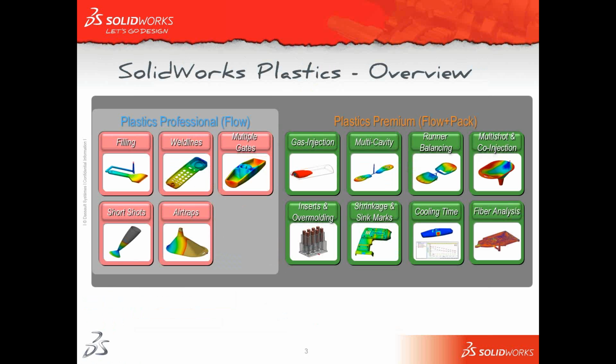This is where, if you've got 2 different sides to a casing, as an example, that are different volumes, you ideally want those to fill at the same rate, just to ensure that they cool at the same time, and you're getting a continuity of quality in those 2 items. So we can actually perform a runner balancing analysis within the system that will alter the dimensions of the injection points that you're using to give us a better fill time that's matched across both components.